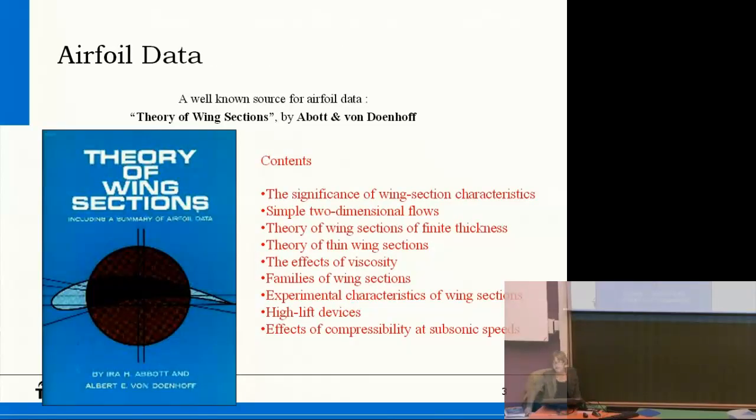Now really the core of aerodynamic design, wing design, is an airfoil. So what people start with is airfoil design, and many airfoils have been designed. And what typically is done is then polars are measured. So lift at angles of attack, drag at angles of attack, so lift versus drag. So for the whole range, people, well, they can, of course, simulate it, so compute it, but eventually they will test it in the wind tunnel to evaluate it.